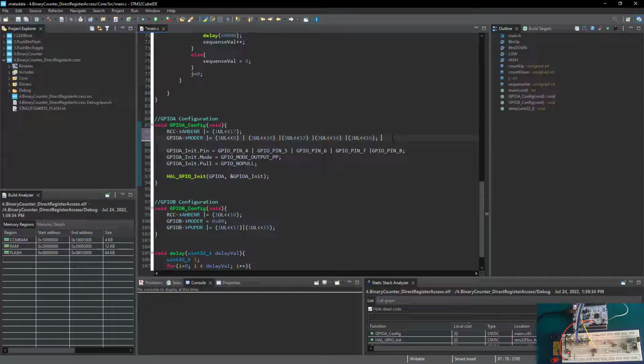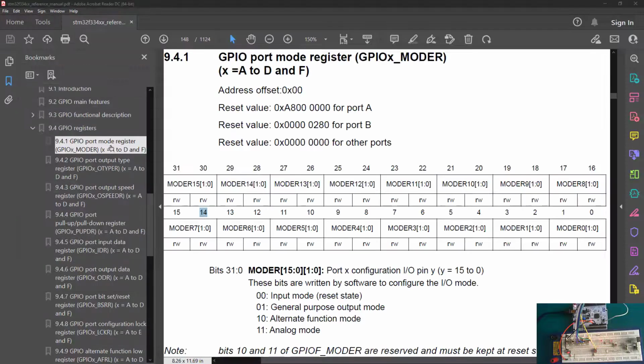So in order to set the pins into a push-pull mode, there is a different register you need to access and set a specific bit. That register is called the OTYPER register. So that is basically the output type mode register. So let's go and find the output type register in our reference manual. So we have to look for OTYPER.